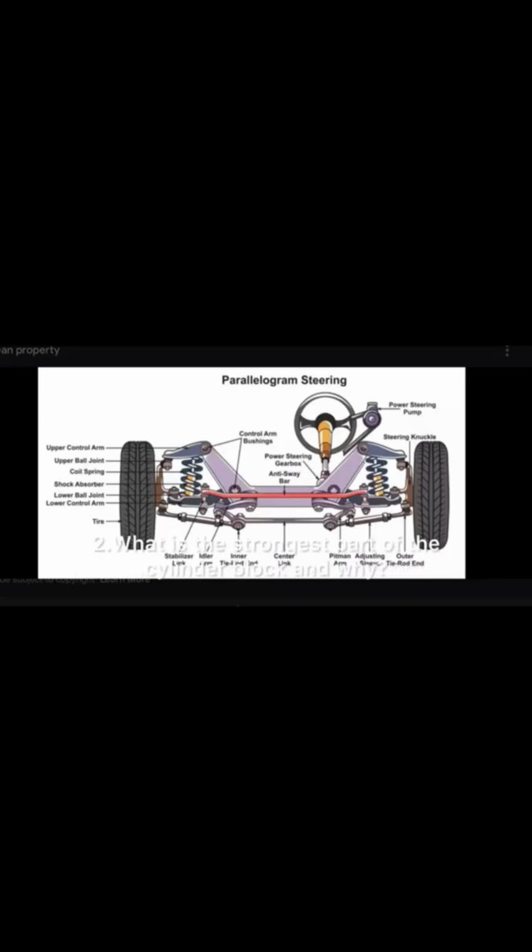2. What is the strongest part of the cylinder block and why? Webs. They need to be able to withstand all of the forces from combustion. 3. What type of casting processes are used in automotive applications? Sand casting, die casting, lost foam casting. 4. Describe die casting Siamese cylinders characteristics. No coolant between cylinders. Very accurate shapes can be made. No internal voids, top of cylinders not connected to deck.